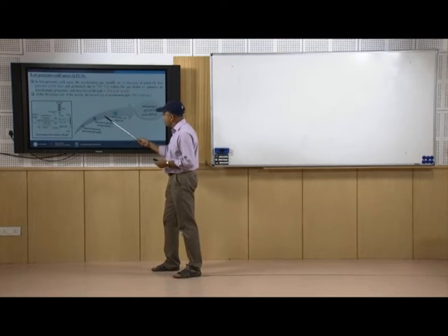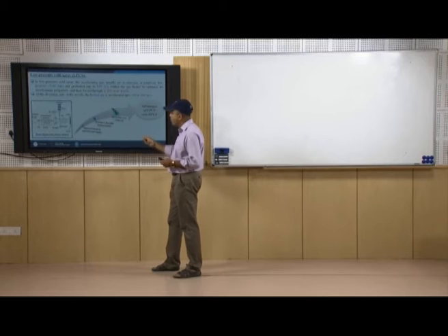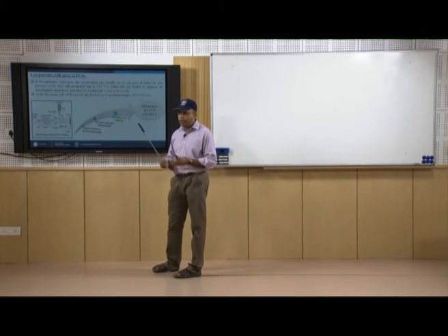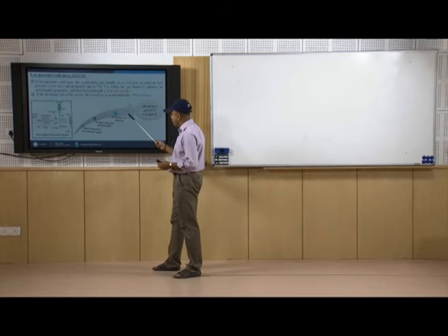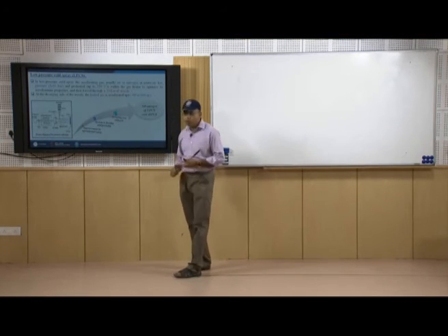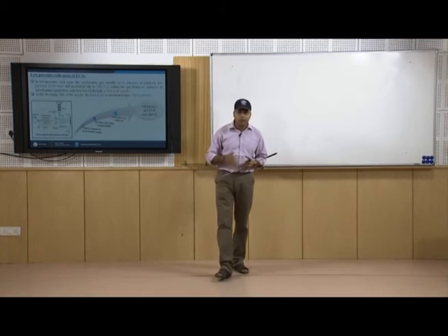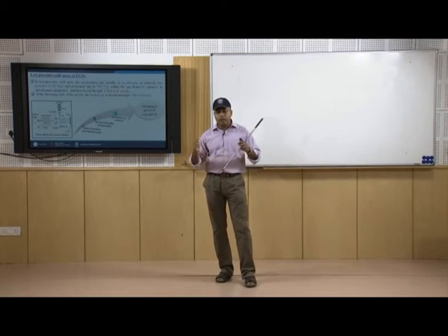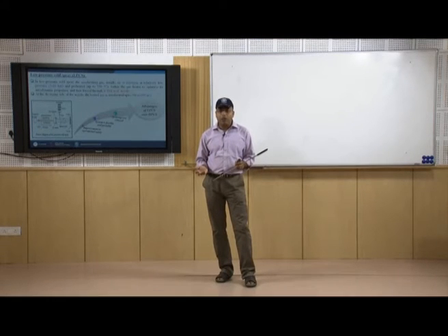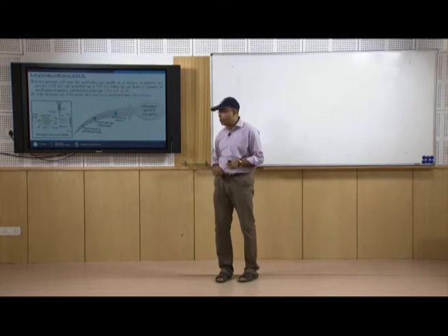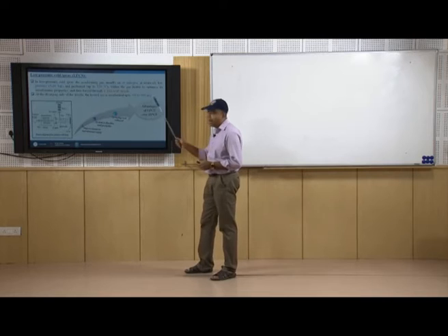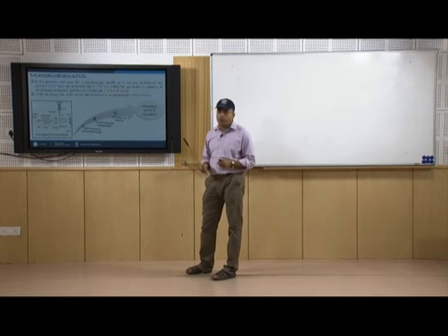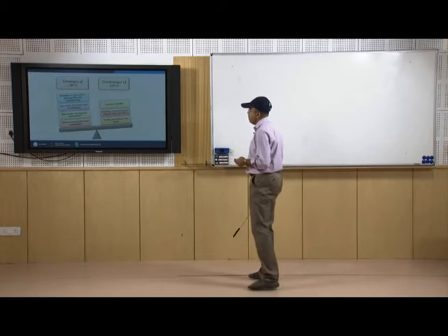Then next is that the system is flexible and portable because you have to generate low pressure and low temperature, and the spraying cost is reduced because we are not increasing the temperature. We don't need any kind of high pressure pump to generate a high pressure, so automatically the spraying cost will be reduced. So these all are the advantages for which we can go for LPCS over the HPCS.